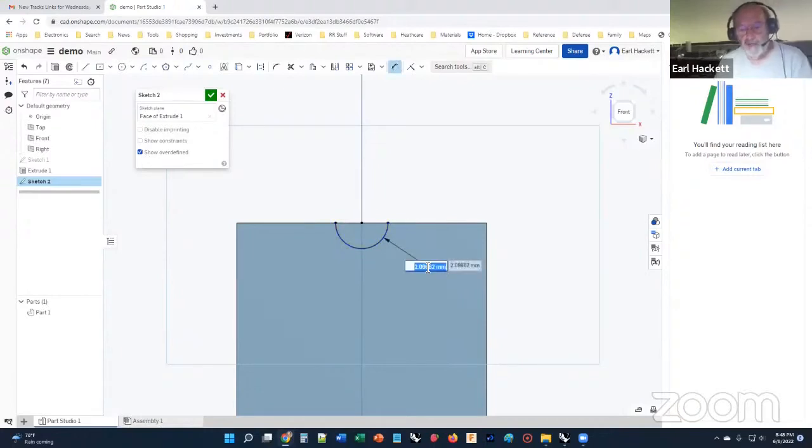and again, you just click on the thing you're interested in, and you drag the dimension away, and now with this highlighted in blue, you can create whatever you want. Now remember, this is the radius we're talking about. So if I wanted a 5 millimeter diameter gizmo, I type in 2.5. Now I have a 5 millimeter.